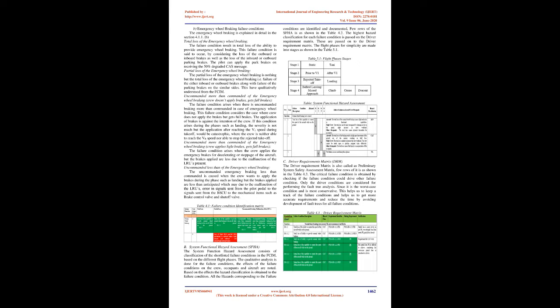A. Normal wheel braking failure conditions. Total loss of the normal wheel braking. This failure condition addresses the total loss of the ability of the normal wheel braking to provide braking. The failure condition is at system level and it considers only the landing gear brakes operation. This failure condition occurs by the loss of both the outboard and the inboard brakes of the brake system.